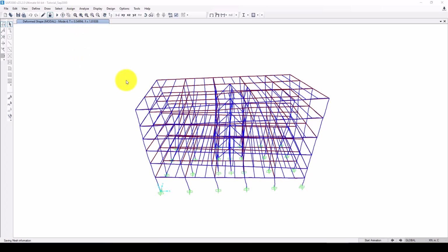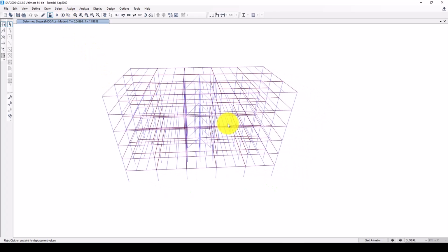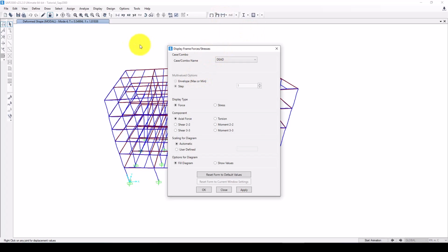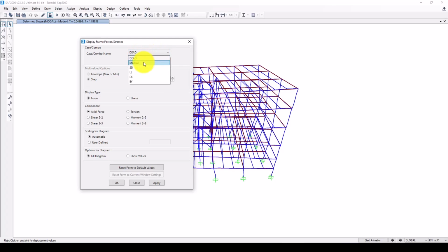We have one equation that's 0.1 times n, where n is the number of stories, times 0.1. So they say it should be 0.6, it shouldn't be less than that, but it's very close, 0.7, which is acceptable for me. And now this is okay. So the next thing is let's see some other internal force in the beam column from the earthquake impact.